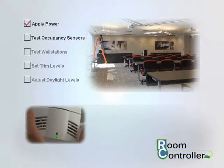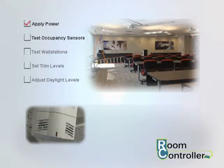During test mode, the sensor will have a shorter 15-second time delay, and the LEDs will flash rapidly when motion is detected. Move around the controlled area, verifying that the occupancy sensor LEDs flash with each motion, and stop flashing when you stand still.